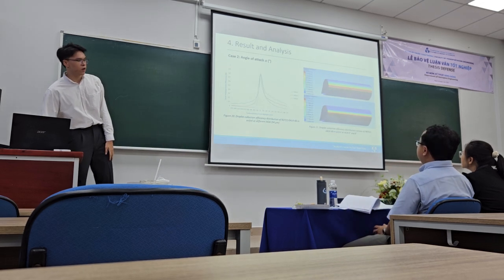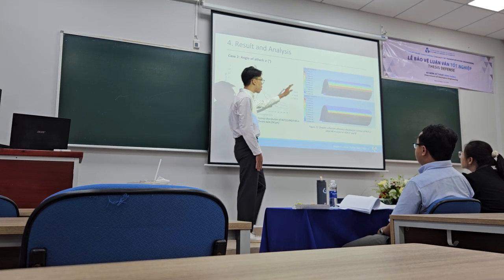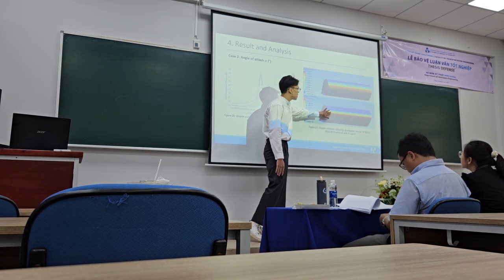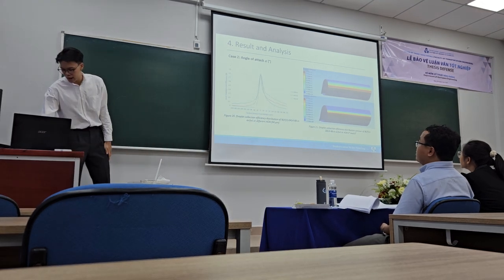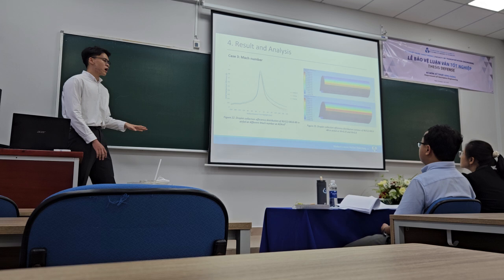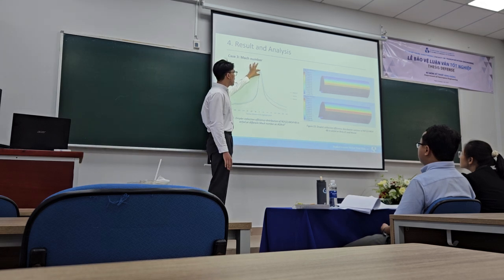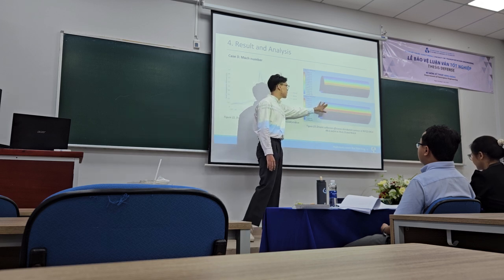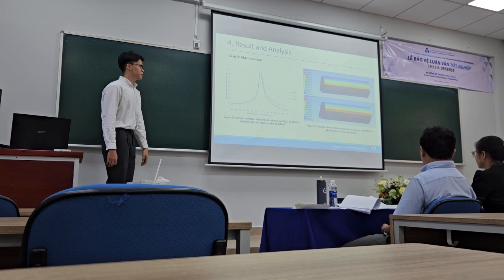Next, we will change the angle of attack. You can see that with the increased angle of attack, more droplets will hit the lower surface of the airfoil. And then we will see the Mach number. With the higher Mach number, this means higher velocity, so it will have more impact. And as you can see on the green, the higher collection efficiency will collide with the airfoil surface.